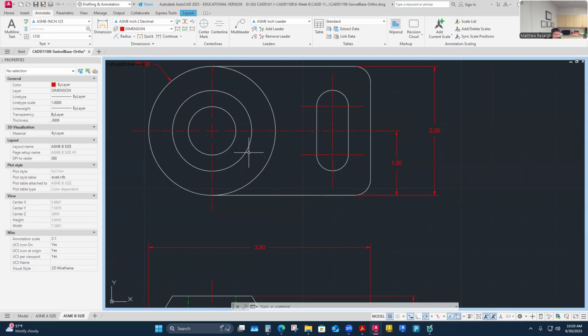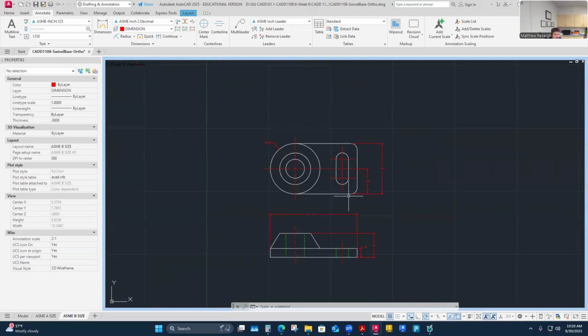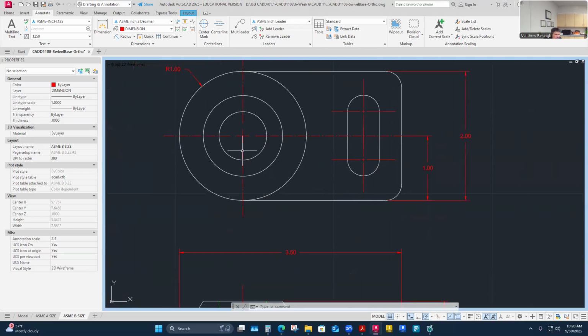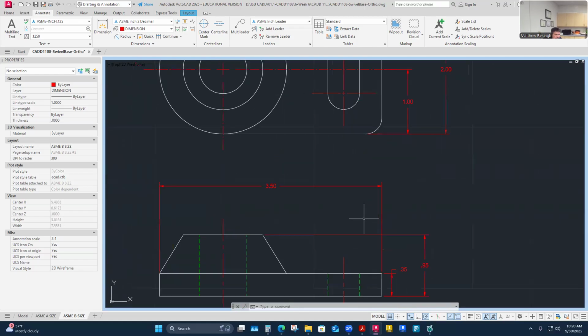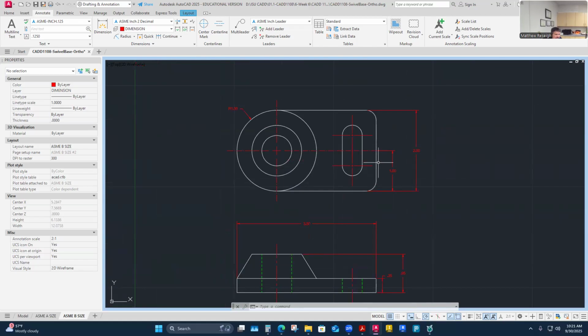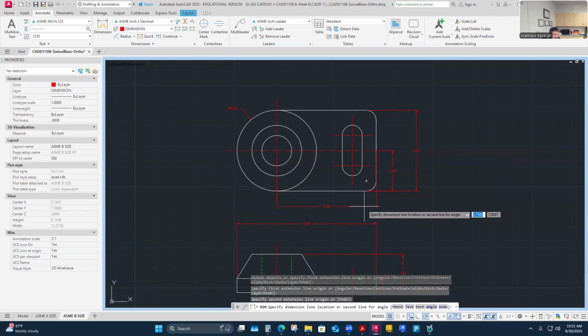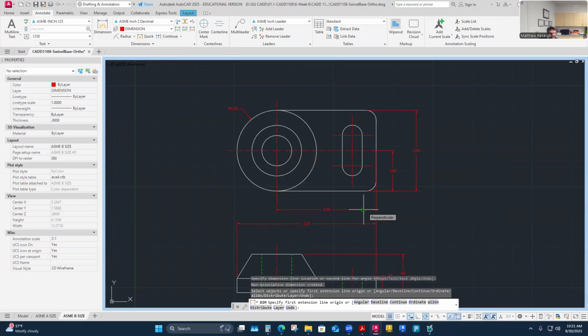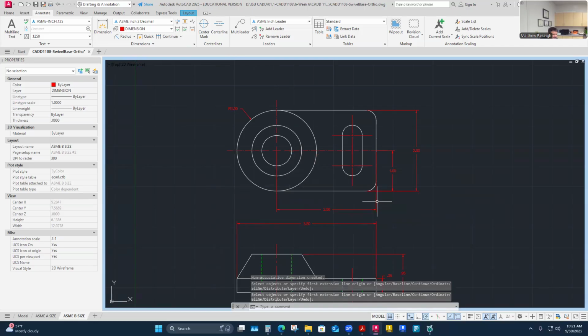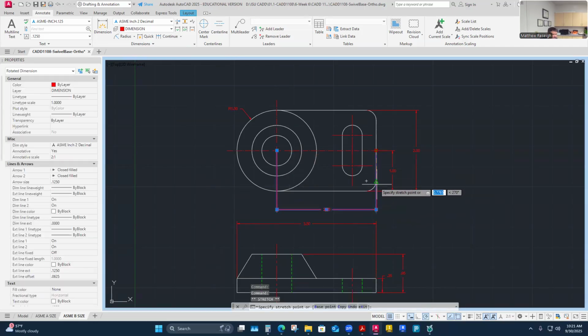What about locating it in the X direction? I could do that here as well. I could do that from the edge of a part over. I think that would be a good control hold. It would be me establishing the right side surface here as a place to pull a dimension from. But I might actually look at it the other direction and say, I'm going to choose this center line here and think about pulling this dimension from it out to this edge. So for a location on the plate, I'm going to add from center out to this edge. That's the way I view this dimension, that it's coming from that center out to the edge, not the edge in. That center line going to the slot, using that slot.